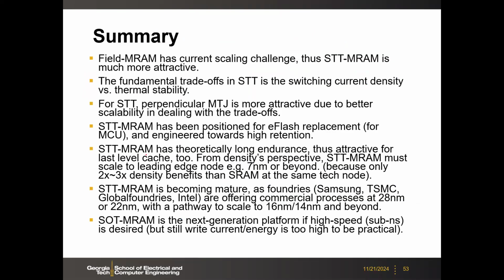Here is a summary of MRAM. STT-MRAM is right now commercially available from all the major foundries, with a scaling roadmap to 7 nanometer and even beyond. And the SOT is still at an early stage, even though it has the potential to be a very fast memory, the only candidate that could have the same speed as SRAM. However, the SOT's write current or write power is still orders of magnitude higher than SRAM. So that's the status of MRAM technology today. All right, I will stop here.